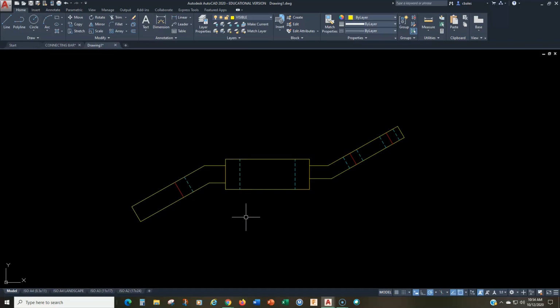All right. So now let's look at the auxiliary views. Okay. Now, if I'm going by the drawing setup in the book on page 167, the auxiliary views are offset from the front view here by 25 millimeters. So that helps me out a lot getting started. So I can go ahead to the offset command and I can offset 25, and I'm just going to offset this incline line and this incline line, and that's going to get me started with these.